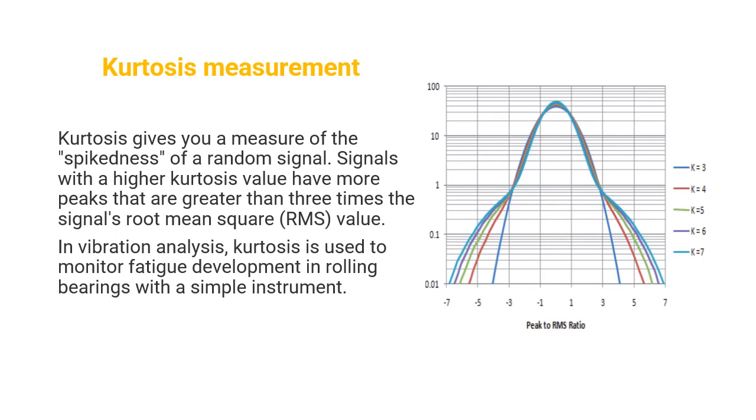I have a full course on vibration analysis techniques where we discuss all this in greater detail. For the time being, just remember that kurtosis measurement is a vibration measurement technique which is used to measure the fatigue development in the rolling bearing.